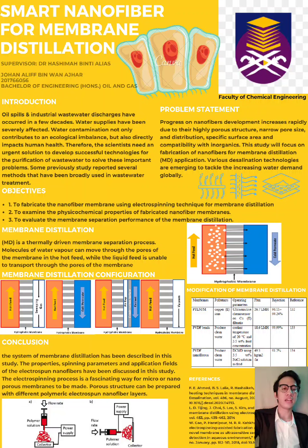There is low conduction heat loss in this setup, making it beneficial for membrane distillation. Generally, due to high pore wetting possibilities, small pore sizes are used in VMD. VMD is commonly used for the removal of volatile materials from aqueous solutions.